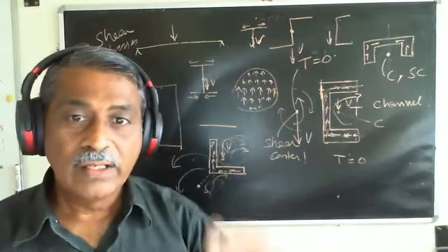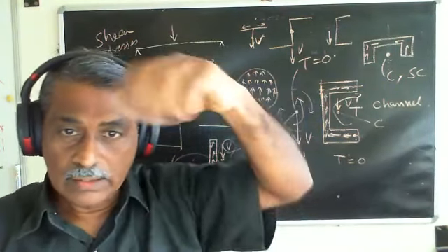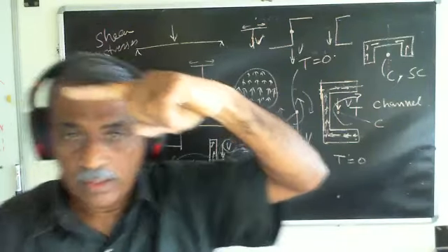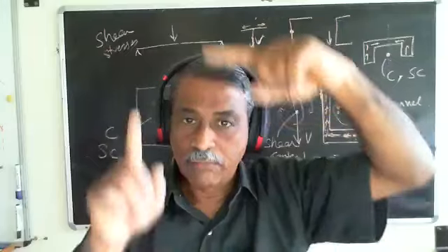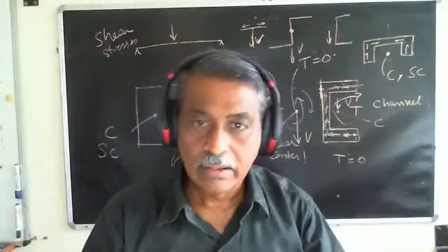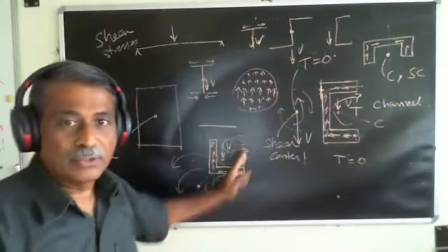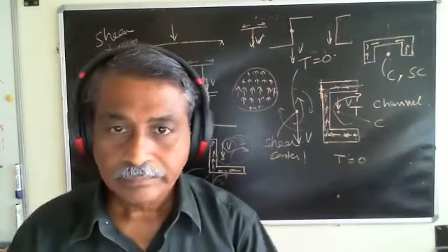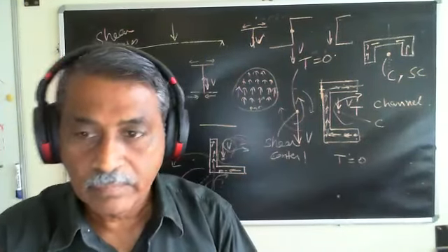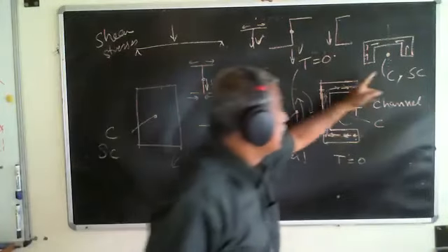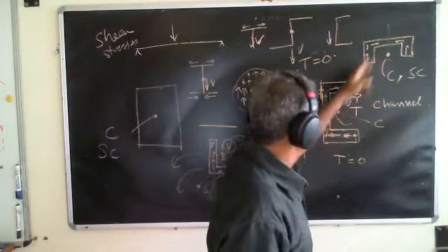Here you will find that there are two directions, one direction upward and the other is y direction. Look at these two direction forces and you get an idea of where the shear centers should lie. Okay. The intersection of these two should be the shear center. Okay. Here also it's the same. Intersection of these two should be the shear center.